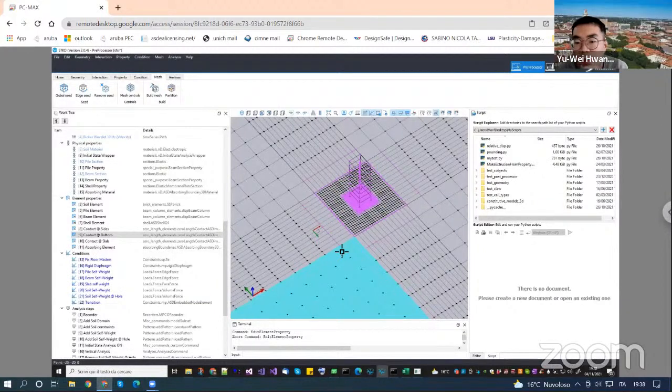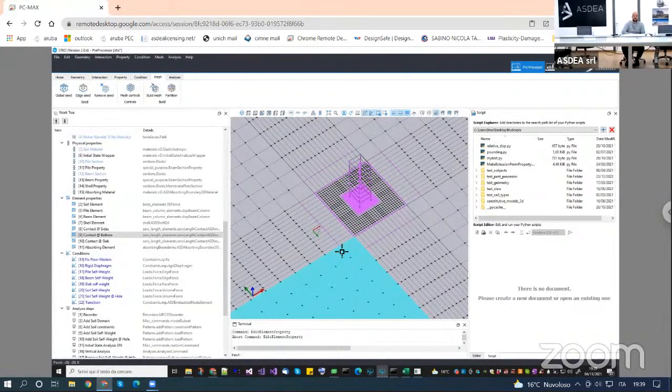Another problem is that the nonlinear soil parameters in OpenSees are all pressure dependent. So that means the G value in the free field column should also be pressure dependent. That's why you need a way to get it from the tangent matrix.